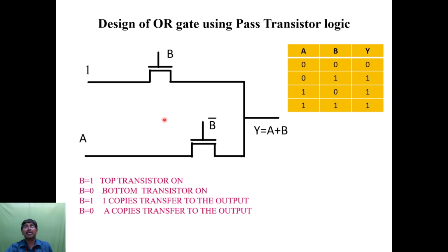So here also we are using only 2 transistors. Pass transistors, these are NMOS transistors here. Just imagine that when you are using CMOS circuits, we have to use PMOS as well as NMOS. But here we are using pass transistors, only a single NMOS circuit. So the number of transistors reduces, and the leakage current also reduces.